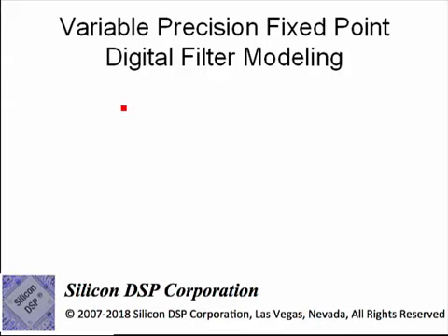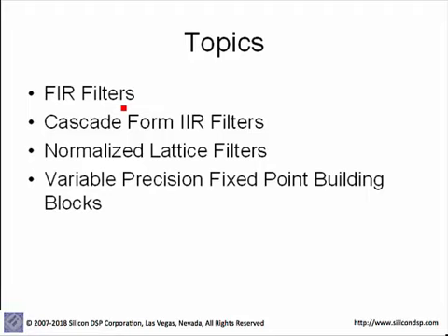An important part of the Capsim filter design package is the support for the modeling and simulation of variable precision fixed point digital filters. We will discuss the modeling of both FIR filters, cascade form IIR filters, and, very importantly, the normalized lattice filters.